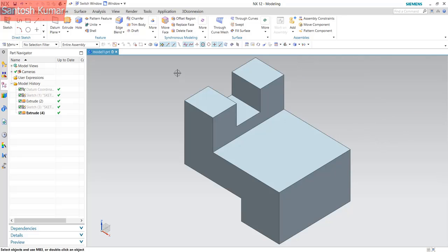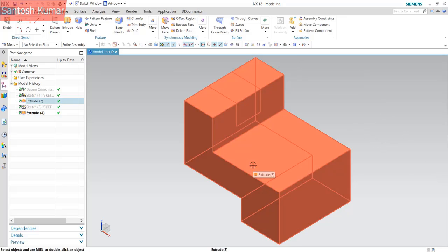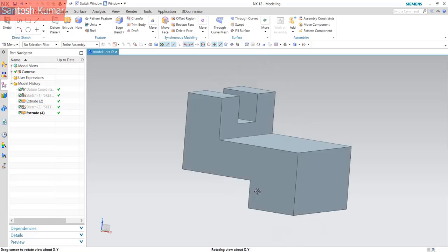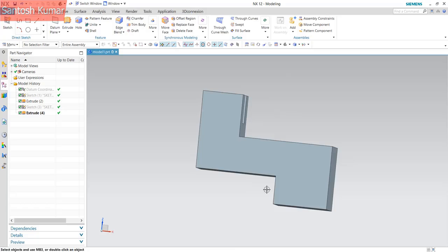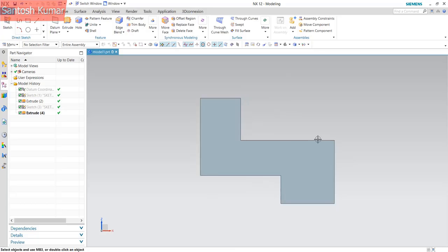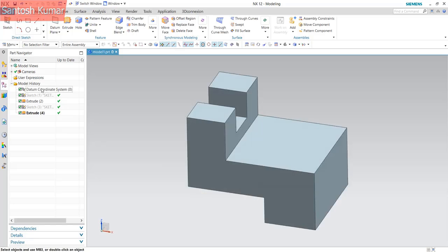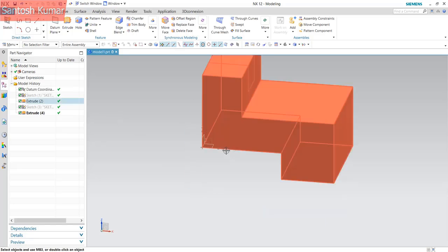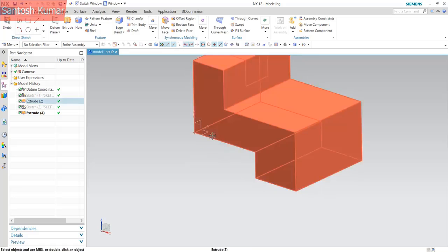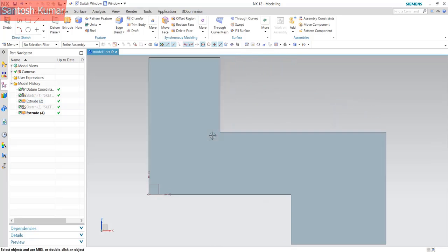Make sure that when you're creating these sketches, you create them the way they're shown in the drawing. For example, in my case, this is the front view. Whatever sketches are shown, I should make sure they are created in the XZ plane. So this XZ plane is my front view. Tomorrow if I press Ctrl Alt F, it will orient to that view, and this would avoid confusion.